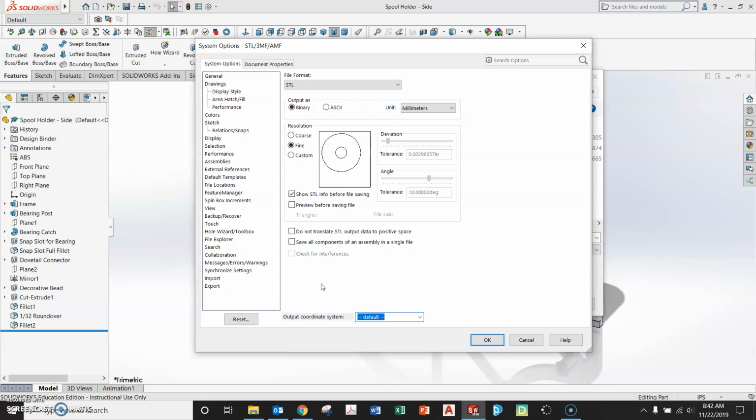So in here, what I would like to point out is that when you go to 3D print something, in our case, we have multiple different types of 3D printers. So we have the large one, the Dimension 1200 ES, and we also have the Digilog from Dremel. We have some Maker gears, and each one uses a different software and different settings. So the Dimension, for example, its software is based in inches. Catalyst is in inches by default. So if we wanted to use that one, I would want to set this to inches.